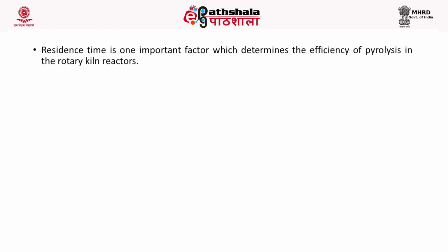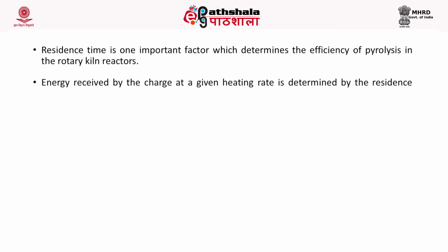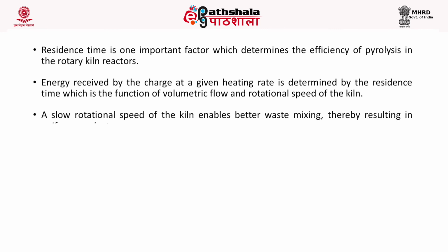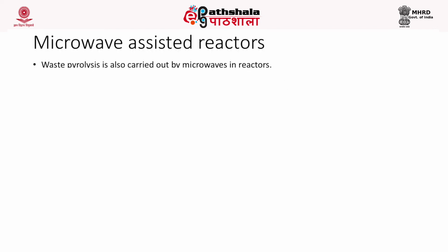The residence time is one important factor that will determine the efficiency of pyrolysis in this type of reactor. The energy received by the charge at a given rate is determined by the residence time, which is a function of volumetric flow and rotational speed of the kiln. A slow rotational speed of the kiln enables better waste mixing, thereby it will result in production of uniform products.